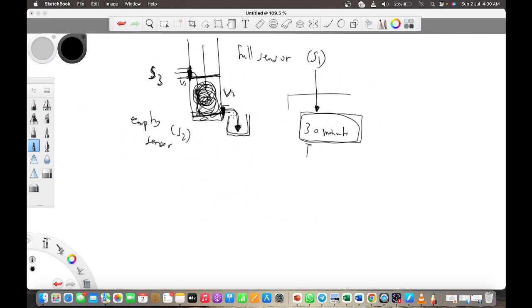Okay. Then there's a counter too. It's a counter that counts every cycle. So once I press S3, the process runs 4 times. When I press S3, the valve opens, it's filled with water, it mixes, is drained, then opens again, mixes, drains, opens again, mixes and drains, 4 times. Then I can press S3 again for everything to run again. So that's the question we'll be thinking about.